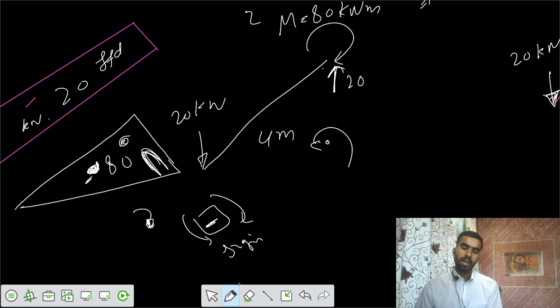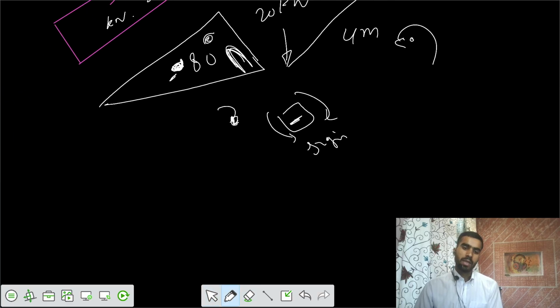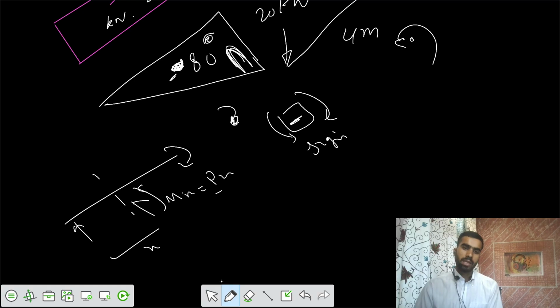Then it's a linear variation with P x, because moment at any x: if you have this load and cut at any section, it is some function of x. Here the moment developed would be M x equals minus P times x.